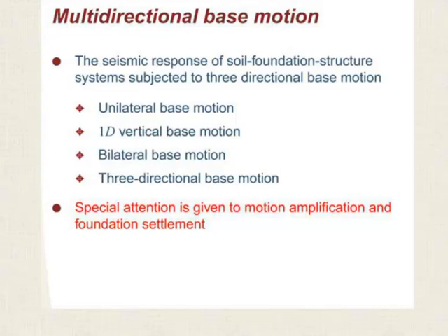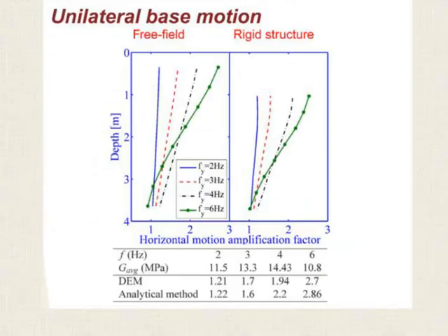There is a lot of information that we can get from these simulations. I'm going to focus on motion amplification and foundation settlement here as key responses. So this is the amplification factor resulting from subjecting this deposit to different sinusoidal motions with different frequencies: 2 Hertz, 3 Hertz, 4 Hertz, and 6 Hertz. As you may see, the largest amplification factor was associated with the 6 Hertz frequency, and that is because that is close to the 7.6 Hertz fundamental frequency of the deposit.